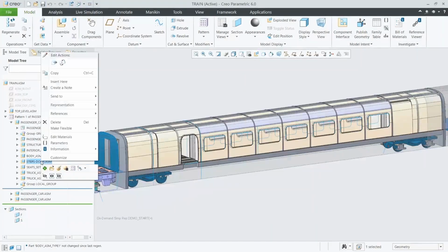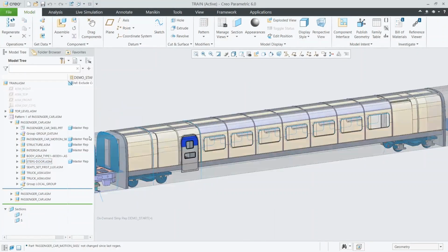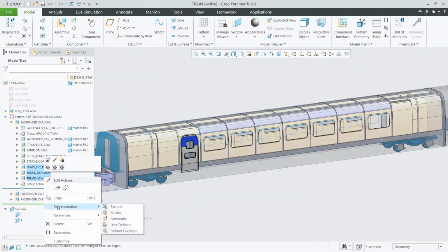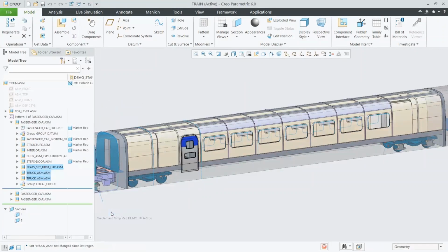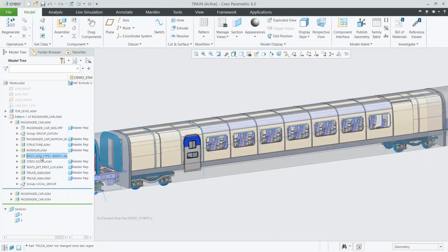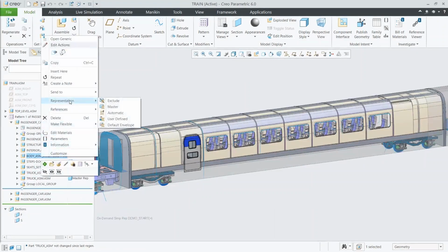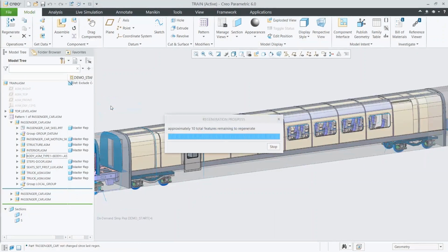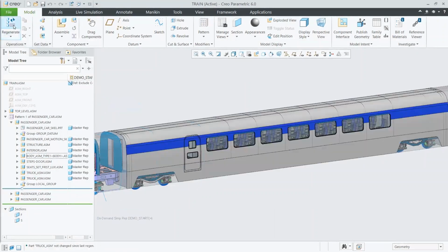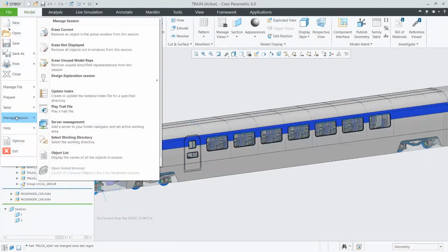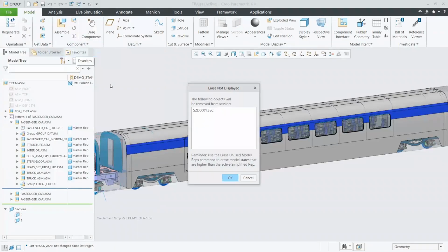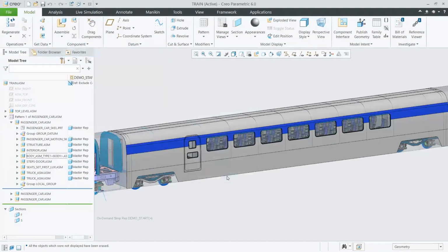So that's again the advanced assembly, allowing me to set those different levels of representations, publish and copy geometry to our different functional areas, and still have all the skeleton models controlling everything that we're working with here. And that's really what you need to do a lot of times in order to work with models of this complexity. Otherwise, you really have too much in front of you. And now that I have it set up to be controlled here, one thing I want to do is show you what it looks like if we need to go through and make some changes.